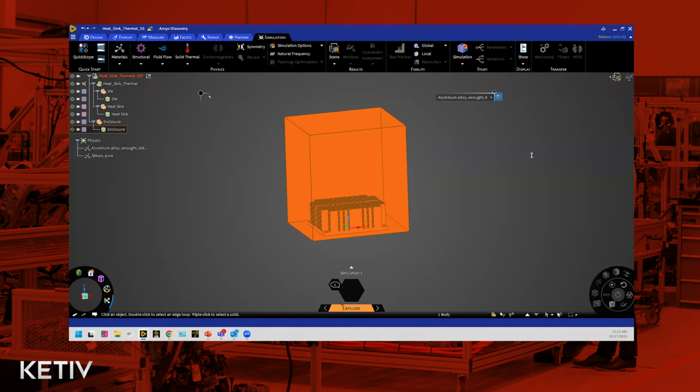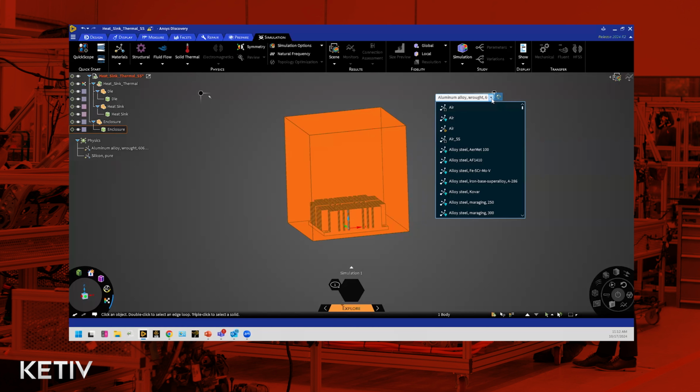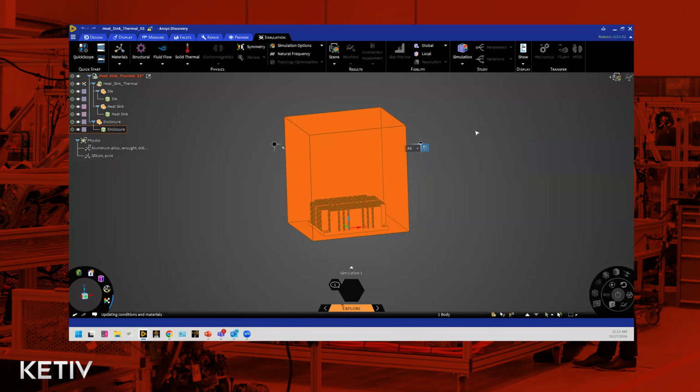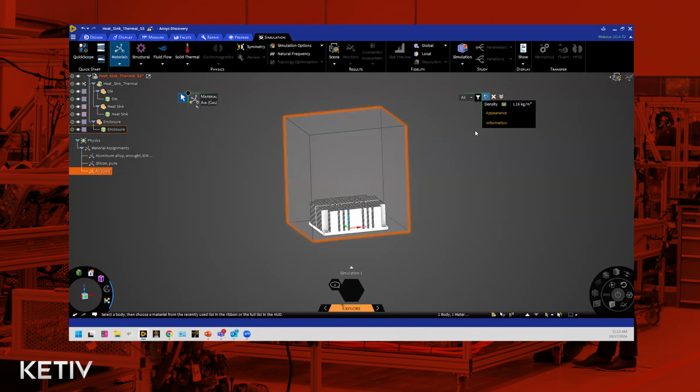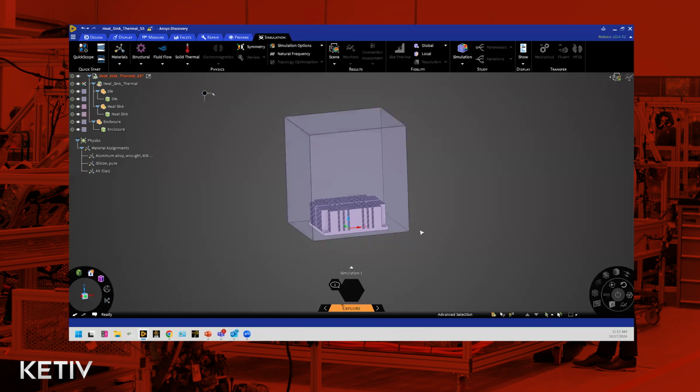And that would also give you the same option. So let's go ahead and choose air. And once you change it to air, the appearance will also change a little bit. You can look at the default appearance properties for each material, and you'll see air in the material assignment panel right now, okay?